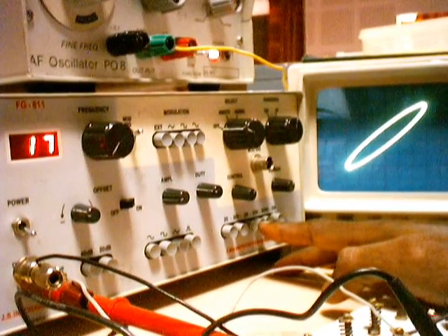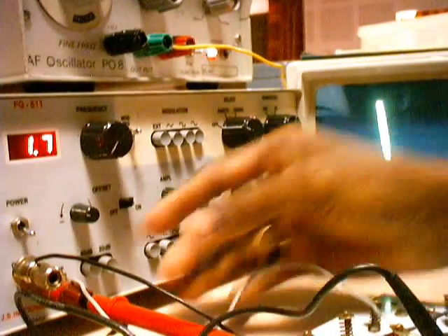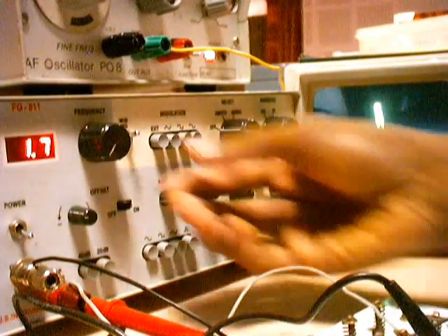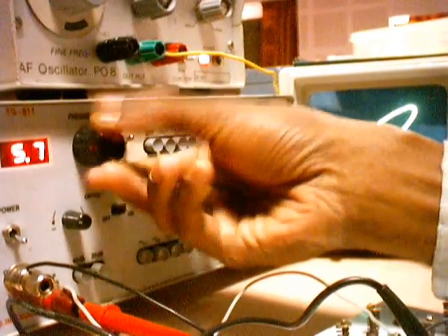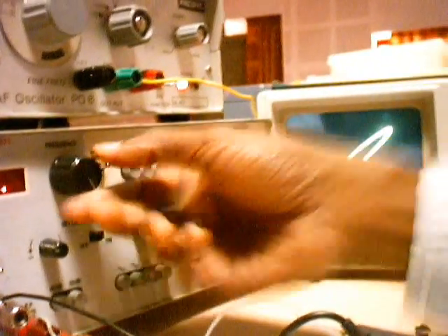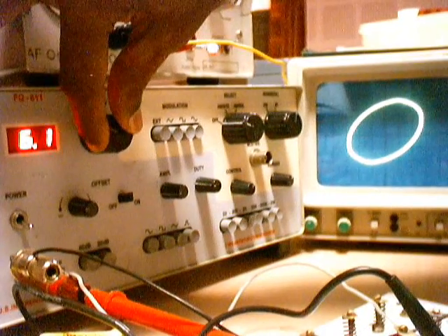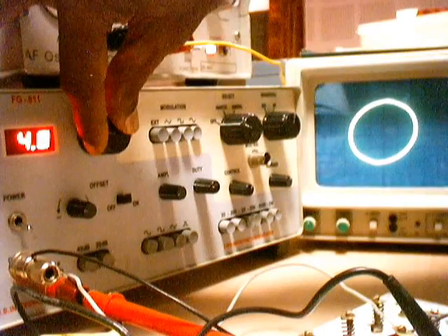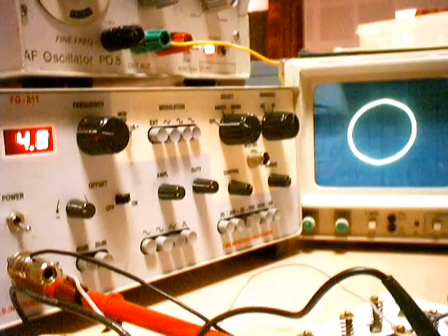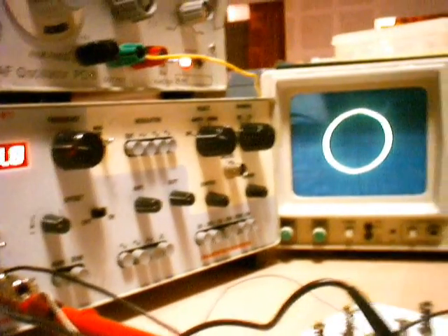Since we designed for 5 kilohertz, the cutoff frequency will be close to 5 kilohertz. So I just switched from the 200k to the 20k maximum range. Let me again reduce from 20k. You can see it's coming closer to a circle. So you can find where exactly it becomes a circle. Can we take this as a perfect circle? Okay, this is a perfect circle.